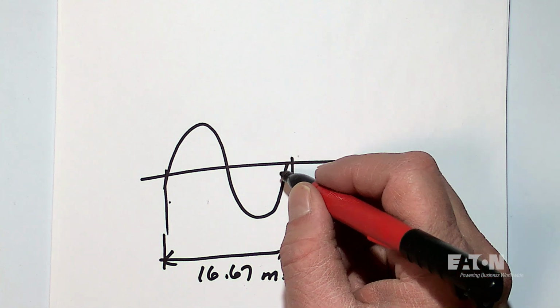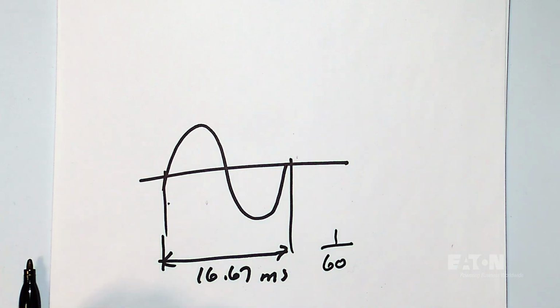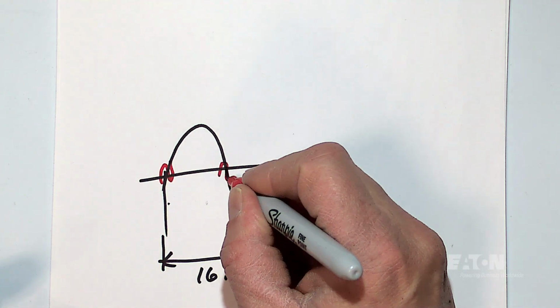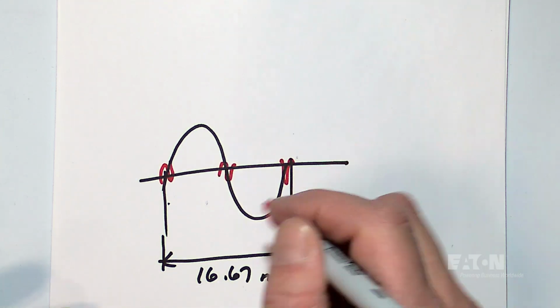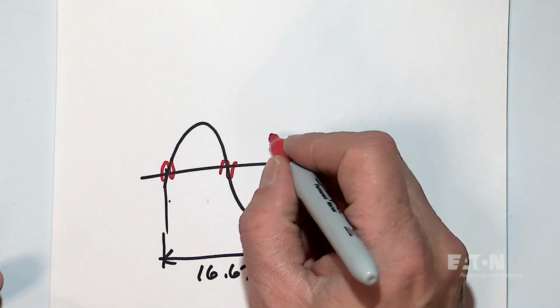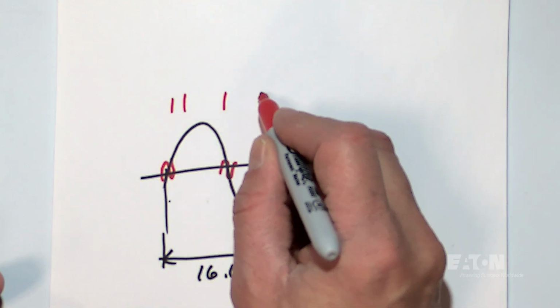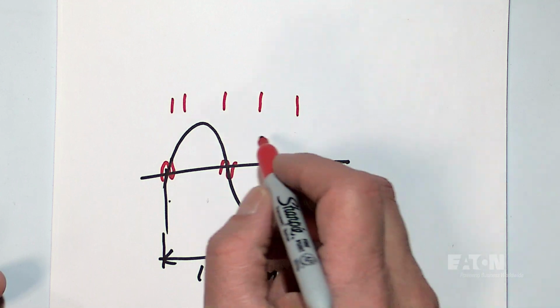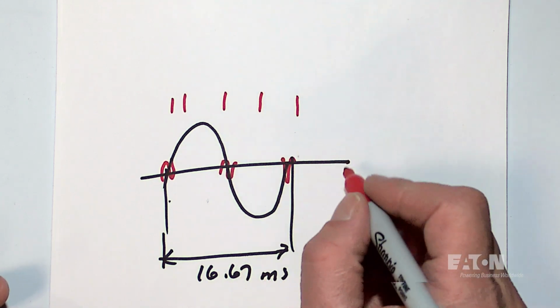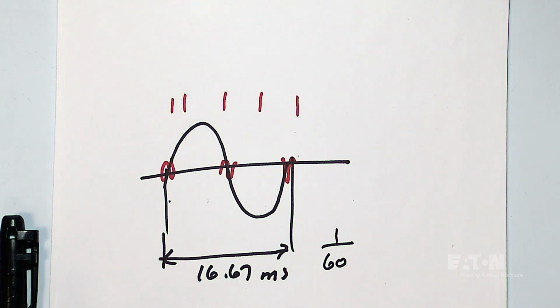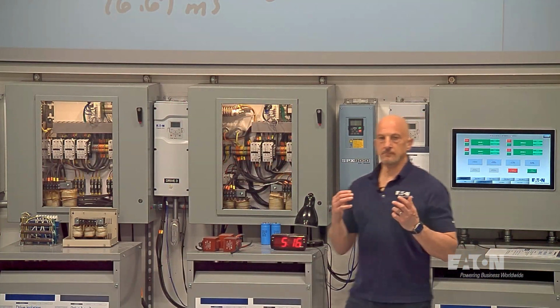So if we want to say that that's normal, but yet we have another situation where the voltage crosses zero, let's say a couple times here, and a couple times here, and maybe even a couple times here. And so it crosses more frequently. Well, the timing circuits now say, oh, this is one cycle, and oh, here's another cycle, and here's another cycle, and so forth. So, in fact, time moves a lot faster. So things like welding applications and anything that uses a digital clock, PLC control, all of those kind of things now become potential problems.